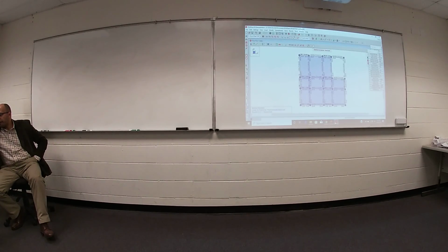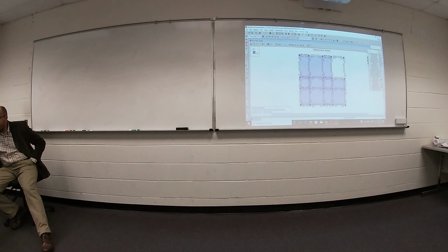If you would like to show up the results on your slab, use this icon, very little icon, model display options, or just hit F2, and then go ahead for slabs. And we need color fill, and your color fill should be contours, and I would like to show up MZ, and then OK. I will see something looks like this.